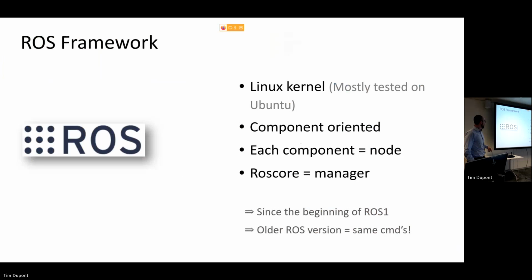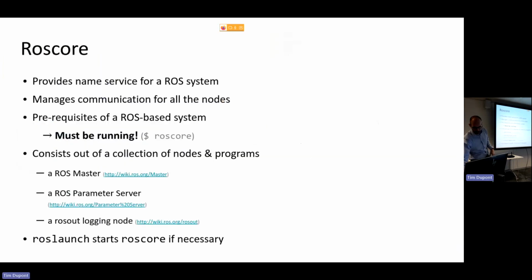So today, ROS1, we're going to create some nodes, and nodes are those processes in the graph to communicate. Each process will be a node. But before creating a node, there's something we have to start, and that's called a ROS core. That's a core process, which will actually be the manager of your system.